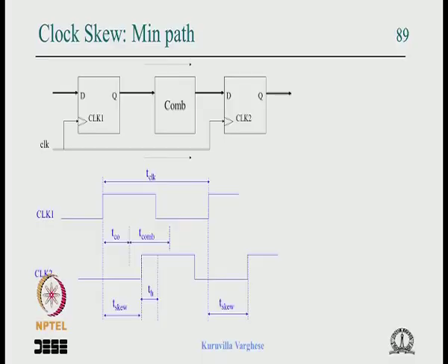But the greatest danger when you look at the diagram is not with respect to one clock edge to the next clock edge. Because clock 2 is getting delayed, normally we assume that it is coming at the same time, and that by the time of this clock edge, the data will change here at TCQ plus Tcom, and we are assuming it is greater than the hold time.